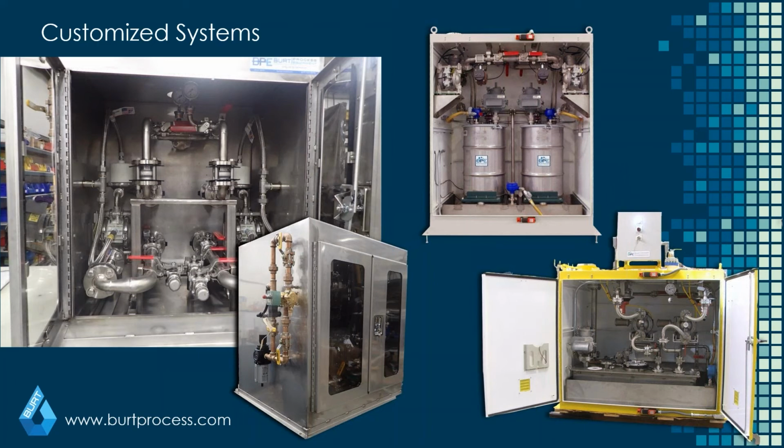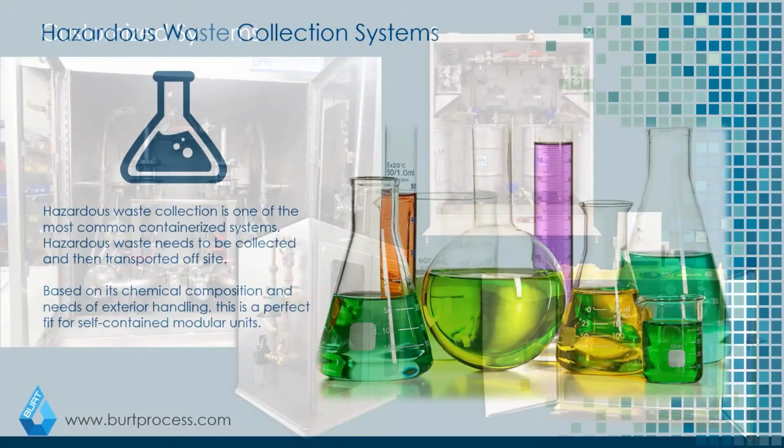And it's often beneficial to locate these systems outside, because very often these types of chemicals need to be hauled off site for treatment. Storing them inside of the building then requires you to have somebody come in and haul them out. This allows you to transfer them into more of an environmental safety enclosure, which can then be accessed from the outside to be removed for chemical safety, or pumped out for chemical safety.